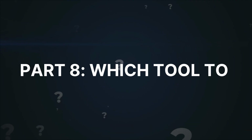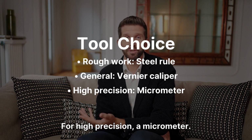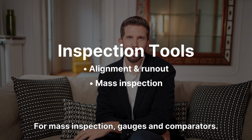Which tool to use? For rough work, use a steel rule. For general workshop tasks, a vernier caliper. For high precision, a micrometer. For alignment and runout, a dial gauge. For mass inspection, gauges and comparators.